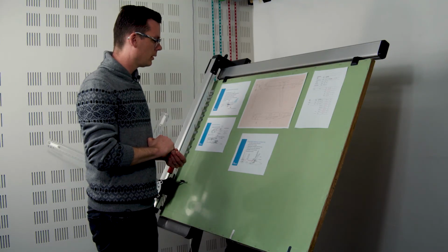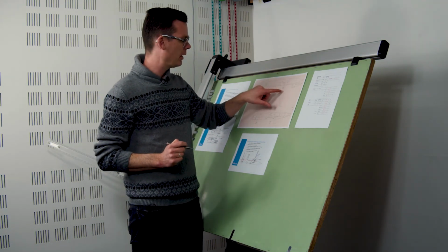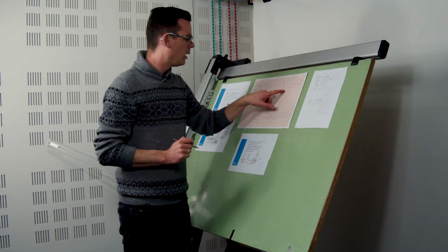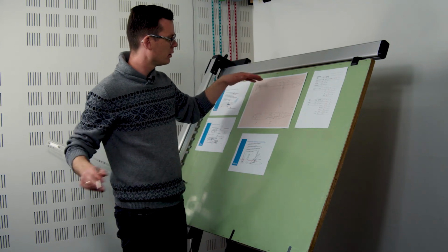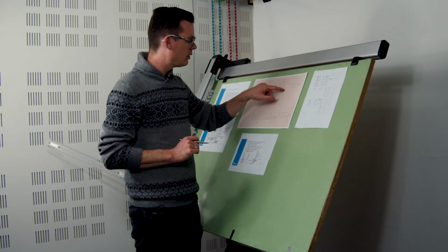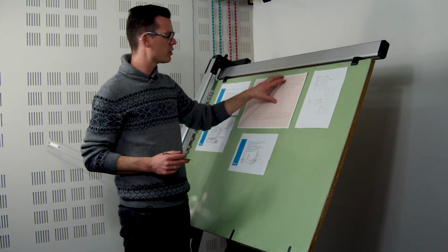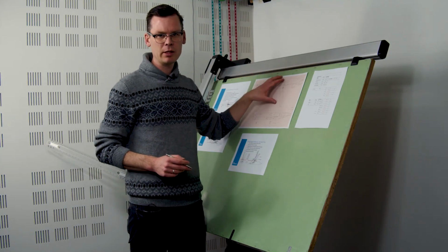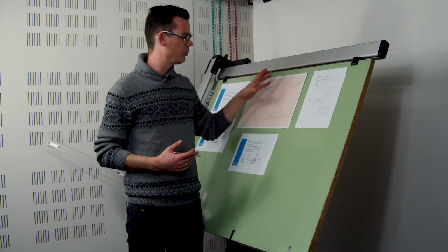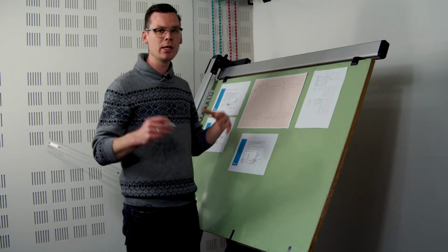Right, so I modified the root airfoil, modified the planform shape, added a trailing edge kink, all to make sure that this undercarriage can actually be retracted. Now, we added a little bit of a triangle here, which means that the surface area of the wing has actually grown. Now, if you perform this as part of your airplane design process, and you started with a certain wing area based on your wing loading and power loading or thrust to weight ratio diagram, then you are now artificially adding additional wing area, meaning that your wing loading actually decreases.